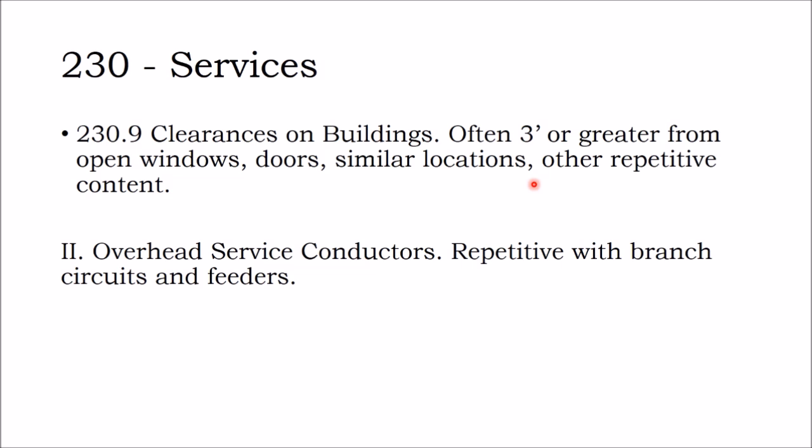code. So we've defined feeders that are supplying service panels, and now we're talking about services that provide and supply power to the building themselves. And they function very similarly to feeder circuits. They are feeder circuits. They have the same safety requirements of feeder circuits. And so as long as you understand that the power lines need to be 3 feet from open windows and